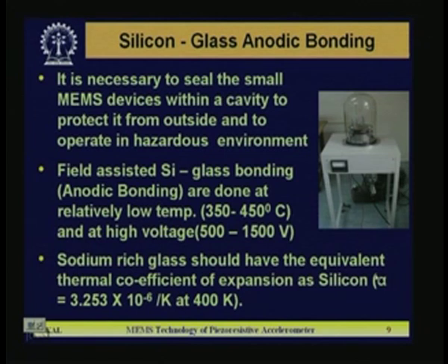Now, first you have fabricated the middle sensor, but the accelerometer structure, you have seen there are 3 pieces, 2 cap layers are there. For your damping analysis you need upper cap layer and bottom cap layer to be delineated, so that during the movement of the middle probe mass, the proper damping is made by allowing certain gas or air with certain pressure, certain viscosity in the gap between the probe mass and the bottom and top cap layer. So next step is design and fabrication of the top and bottom cap layer.